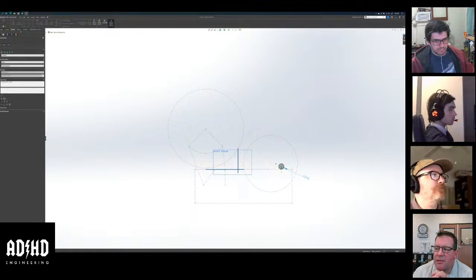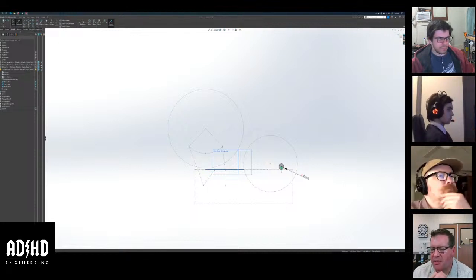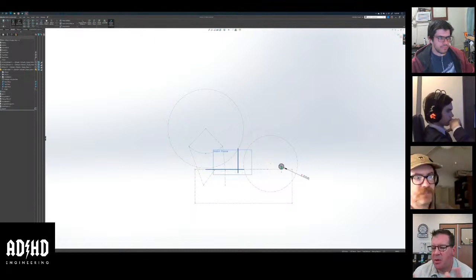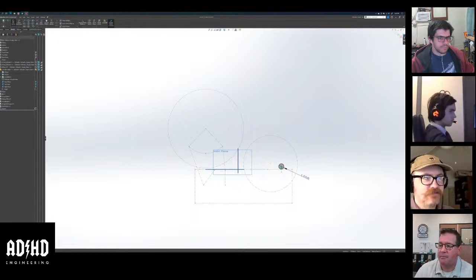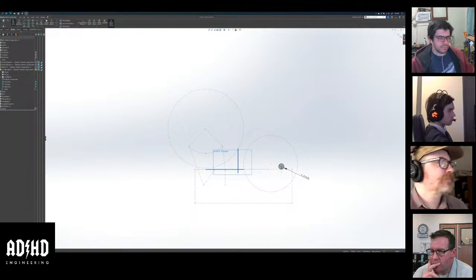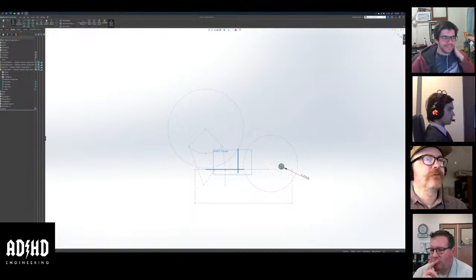Or actually, we never really added it. So my question is, I'm pretty sure you don't have the width of that roller when you extrude it, right? Which we want to be at 72 millimeters. So if you can extrude that, that's a secondary thing. It's not in the sketch, but that's a parameter, right? So can you extrude that? Yeah. And when you give that variable, make sure that variable is not in the part, but is in the assembly.